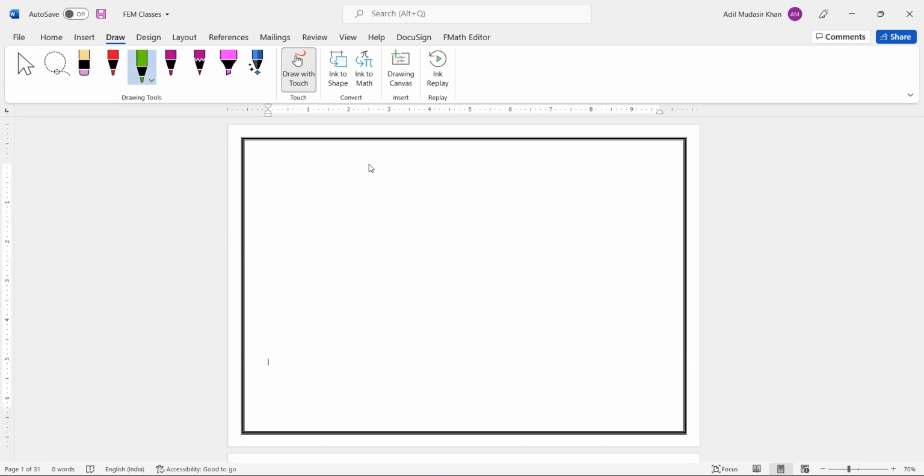Let's suppose we are having a bar. Now this bar is composed of two elements. So this is element 1, this is element 2. This is node 1, this is node 2, this is node 3. On node 3 we are applying force F, and at node 1 we have force R. And be careful about this node 2. This is an internal point. The summation of all the forces on this node has to be equal to 0. Okay, so first of all, take element 1 into consideration, right?